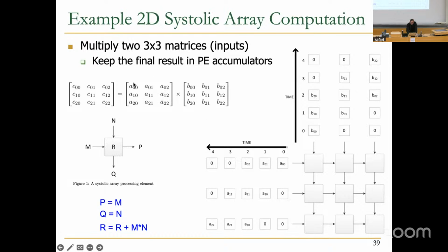And that's exactly what we want. A00, B00, A01, B10. And then next cycle, A02 comes here and B20 comes here, and you add to whatever was stored over here, A02 times B20, which is really the dot product of this vector with this vector, right? That's beautiful. And you can convince yourself that everything works as expected, and in the end, in these cells, you get the C values that are calculated mathematically with matrix multiplication. Okay? So that's beautiful.